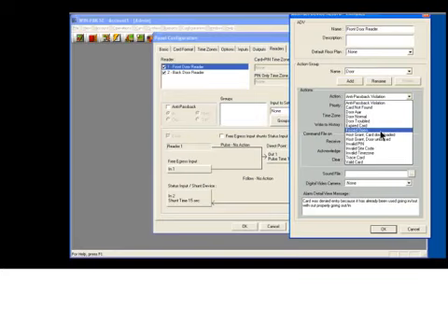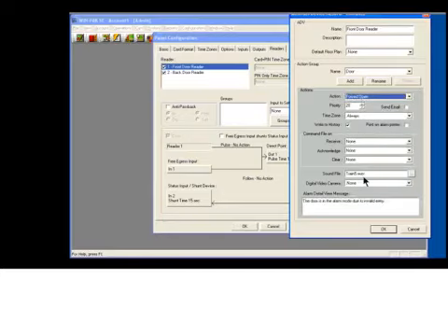You'll see you have a long list of choices in here. On an anti-passback violation, I can make something happen. On a card not found, on a host grant, any of these different things, I can make something happen. In this case, when a door is forced open, I want this camera to pop up.